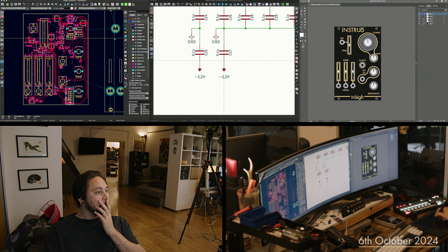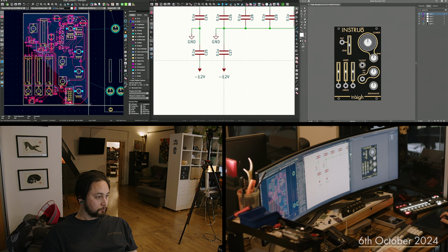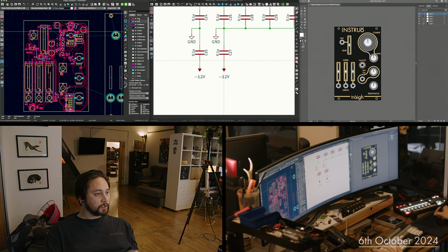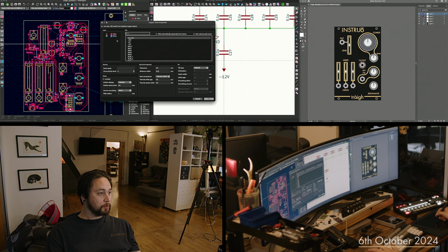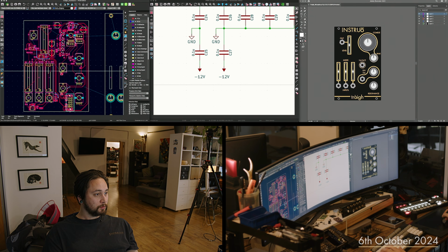Ground to go. Let's put the ground plane on the bottom layer. So what I'm doing here for the ground plane, select the layer I want, although that can be modified during the process, and then it's this selection here, add fill zone, or option Z, pardon. There we go, that's cool. Bottom copper and net class I'm going to set to ground. Just leave the default settings.